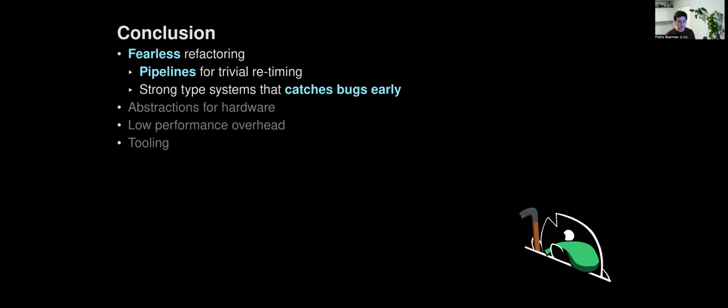And it was super slow. But I realized that UltraRAM can be extremely pipelined. Like you can have 20 pipeline stages and get better results. So because I was able to do this fearless retiming thing, I was able to just add pipeline stages until I hit my Fmax. I didn't have to think, I didn't have to change any code, apart from changing where I put registers. So that was very pleasing.